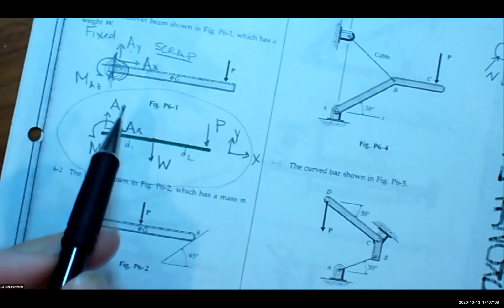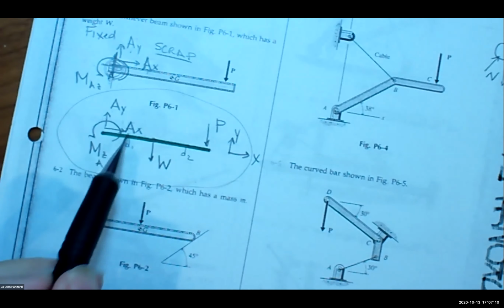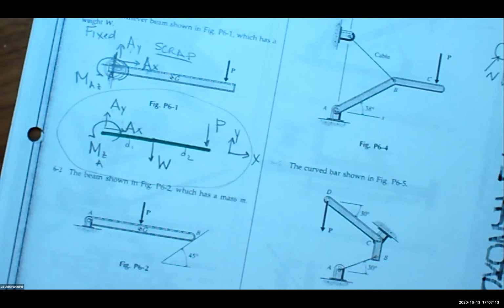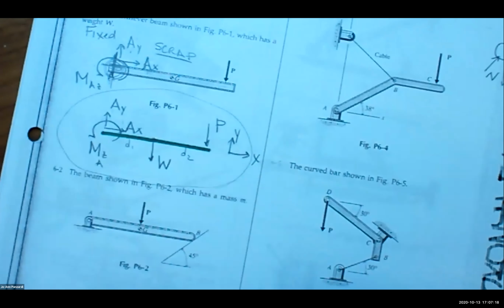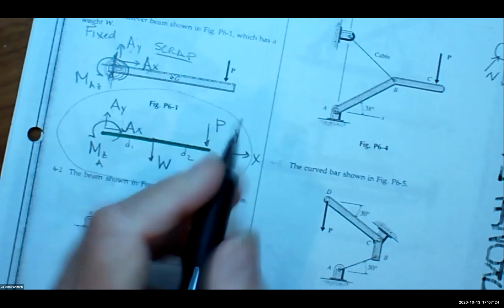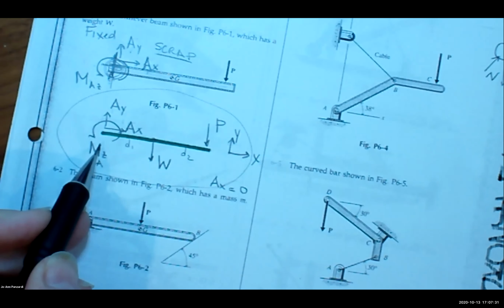And so we draw in all of those reactions just as stand-ins, even if, as you're saying, because this is relatively simple, we can see there's no X force. That's right. When you go to do the sum of the forces in the X later, you're going to find that AX is 0, right? Okay. But you have to draw it because a fixed support can withstand an AX. And then you have to do the equilibrium equations, or you could say AX equals 0, but you have to draw all the possible reactions at the supports at each support.